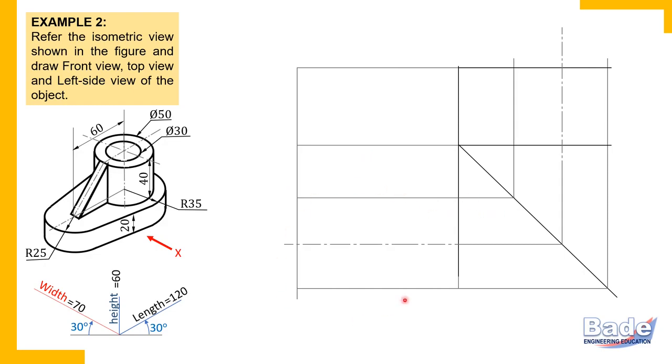But for the top view, it is a symmetrical view. Draw that axis of symmetry, front and back, two identical portions. Front and back, two identical portions. This is the axis of symmetry in the side view. So if an object is symmetrical, it is better to draw the axis of symmetry initially, just after drawing the rectangles. Okay, and now we'll start drawing the views.